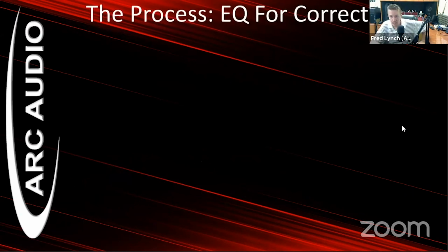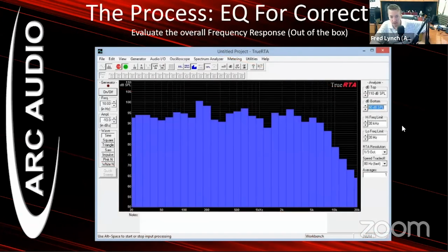So when we look at a system and we're looking at a frequency response, this could be an example of one system that you're looking at the overall reference of what that response in that vehicle is. If I was hooking up a system and based off crossover points, if I looked at this RTA right now, the first thing I would be doing is making sure that my tweeters were hooked up or even turned on, because at a 5500 hertz crossover, there's very little information beyond that.